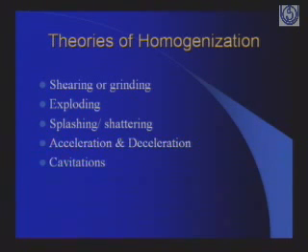When milk is forced through the very fine homogenizer valve, it is forced through at a very high pressure. After leaving the valve, the pressure is released, and because of the very high pressure inside the fat globules, they explode and are broken down to a smaller size.